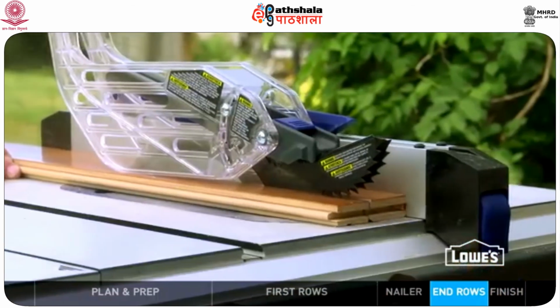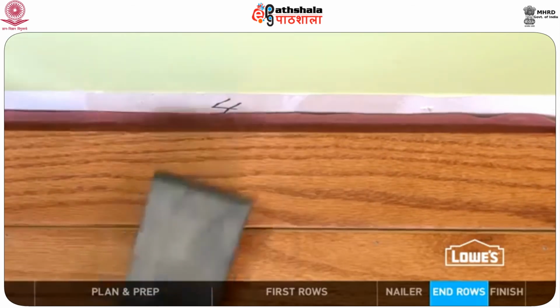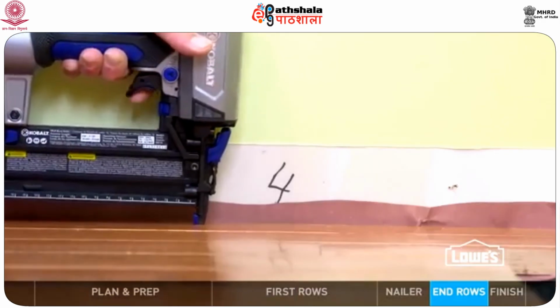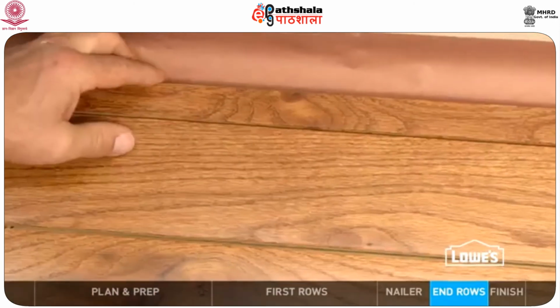To fit the very last row, cut the pieces, keeping in mind the expansion gap. Use a pull bar to wedge the pieces in place. Then face nail. If the last strip will be less than 1 inch wide, glue it to the previous row.